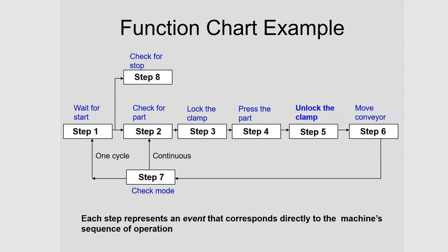If you think about ladder logic programming, you can just write one long ladder rung, and as you'll learn in a couple of weeks, there are instructions you can use to jump around the ladder, to move to different parts of it, to move back and forth in the program. So you can make an adjustment early in the program that can have an unexpected effect in other places if you have a lot of lines of code. With function chart programming, since each individual step is its own program, maintenance is a lot easier.